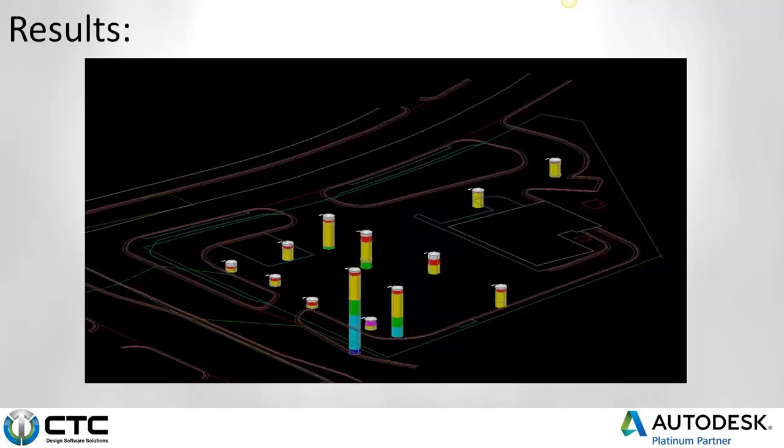And at that point, it will load in, and you'll see 13 soil boring holes in there that will pop in right at the location of the northing and easting. Obviously, you got to make sure that your CSV file is on the same coordinate system that your drawing is on, because it won't do a coordinate conversion for you.